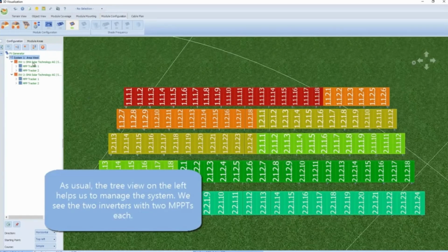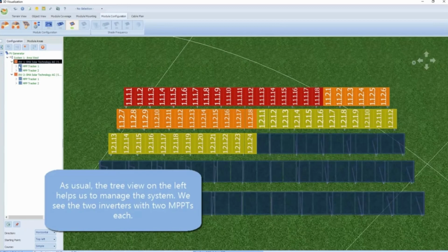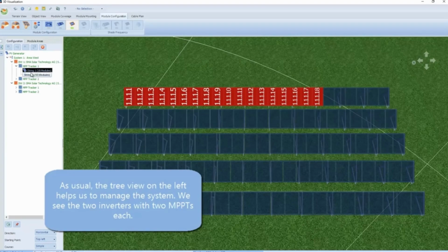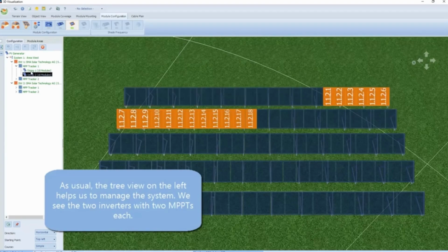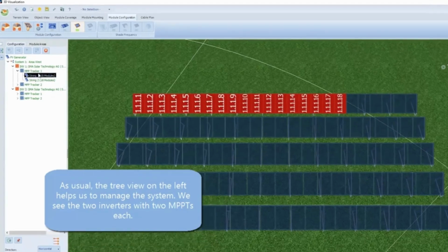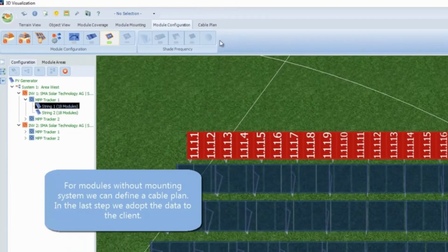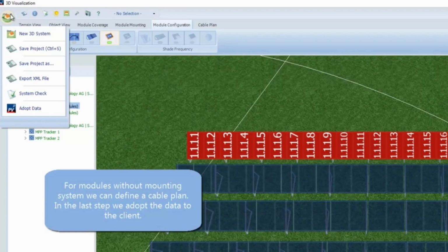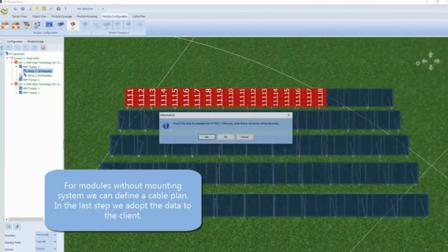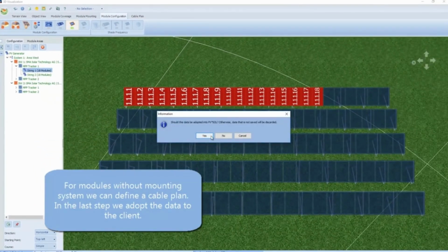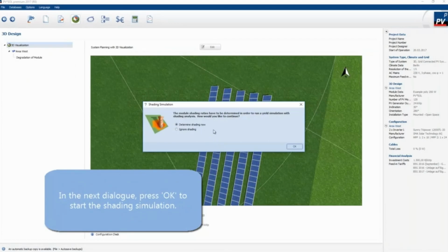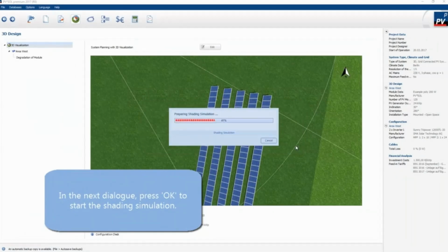Here we saw what I mentioned before, the loss is due to the shadowing, so the red part is subject to shadowing, the green part is okay, the yellow part is almost okay, and so on. So you can have different thresholds. And best is to interconnect the modules which suffer from the same shadowing to one inverter, so the good ones wouldn't be affected by the reduced current from the shadowed rows of modules.